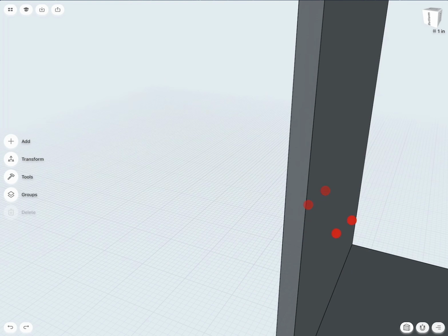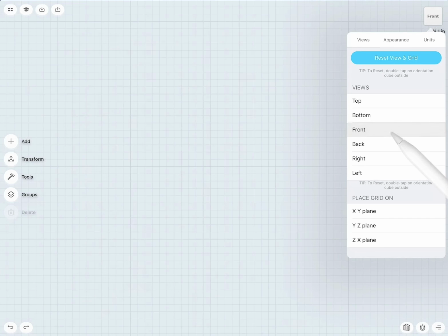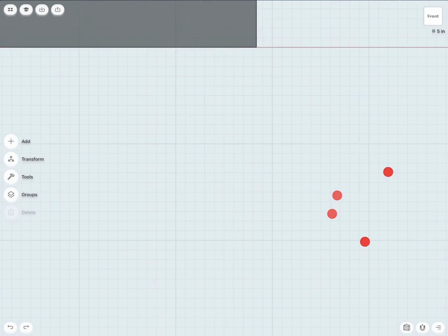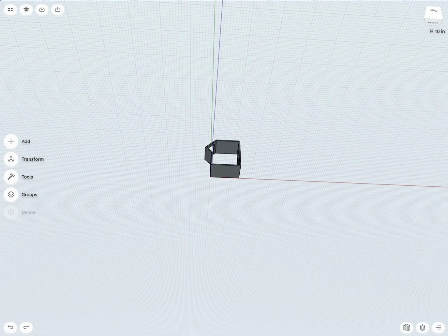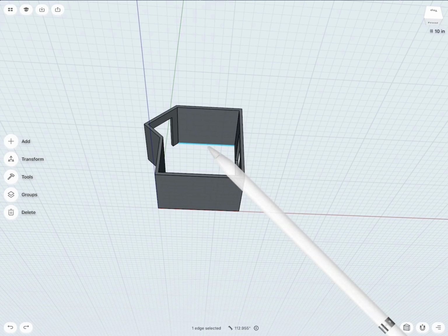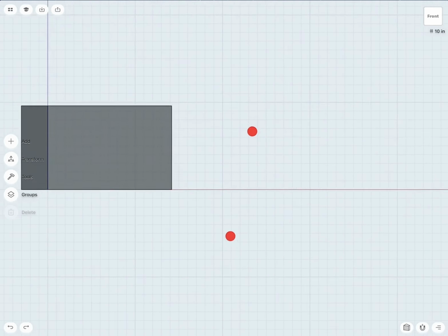So an easier way to do this, I found, I will just go to the front view here in this case, is I will simply draw this element somewhere else. And then I make a small extrusion of that profile, and then I will move that 3D object to, let's say, this edge, and then I sweep it. So let's try this out so you see what that means.